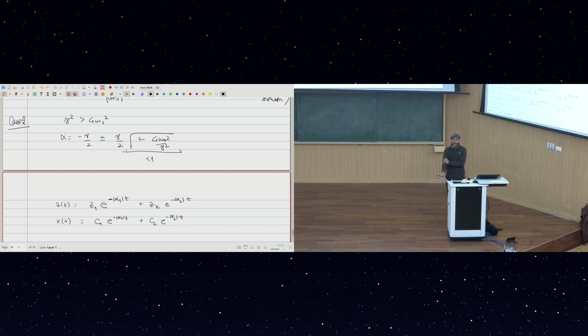Unlike the case 1 that we had, if your damping is large enough so that gamma exceeds 2 omega naught, you have a large damping, that's what you need in a door. You open it, it closes. It never hits, because you will see it's asymptotically decreasing to 0. It will never hit. But if you have a door opening on both sides and you have an underdamped situation, it will do this. Or if you have a strict stopper, then it will hit, it will want to go the other way around.